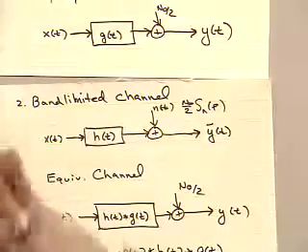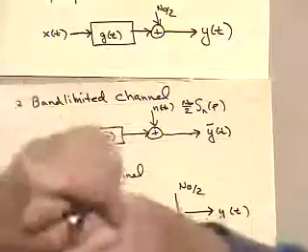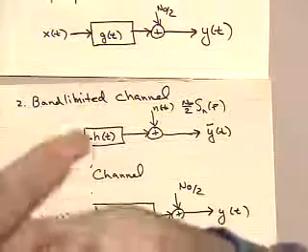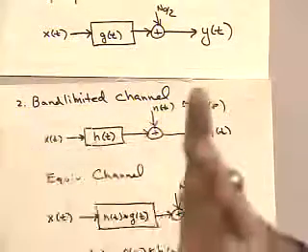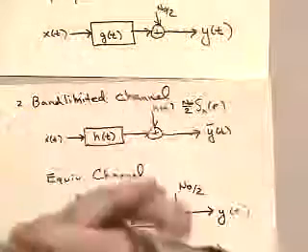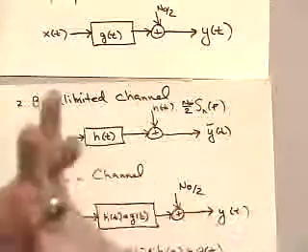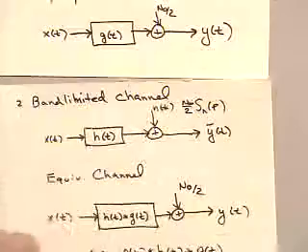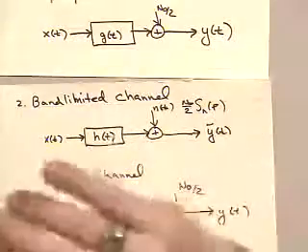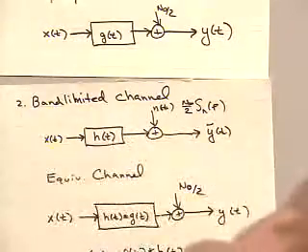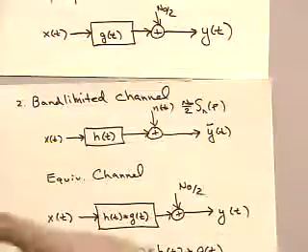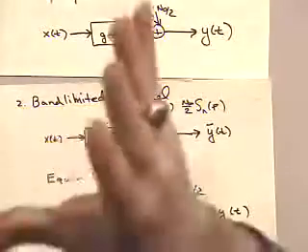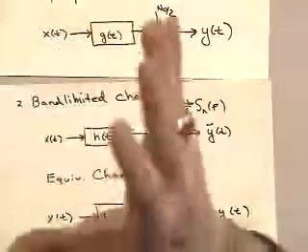So now we've set up a fairly powerful theory, okay, at least in terms of modeling things, where we've got this complex signal. So we've got PAM, QAM, QPSK, all on the same terminology. Okay, we can handle correlated Gaussian noise as well as white Gaussian noise. We just have to put this whitening filter in, and we've got a model for all of these different types of modulation techniques, and basically any type of linear channel and any type of correlated noise.